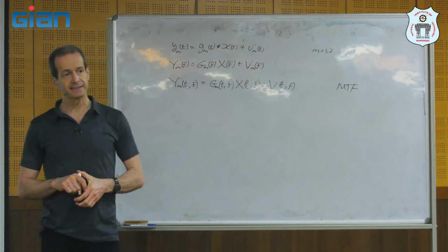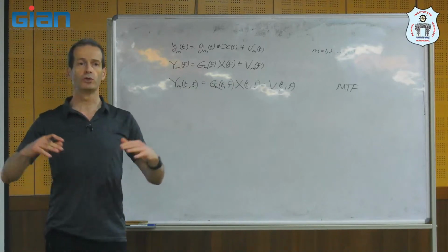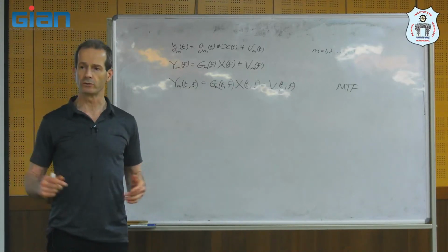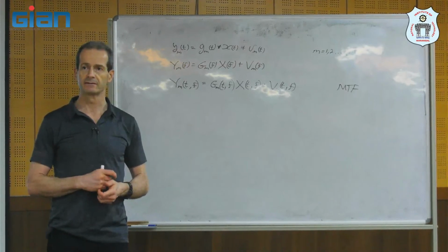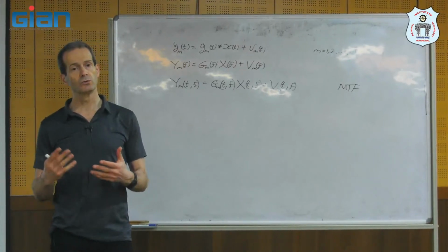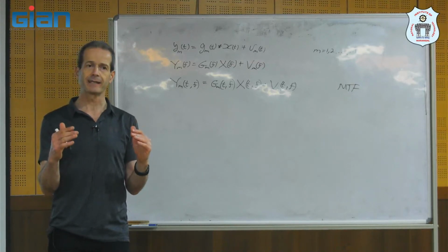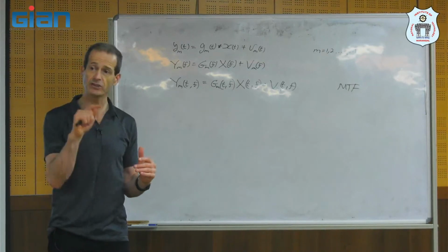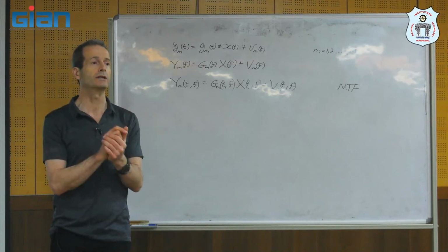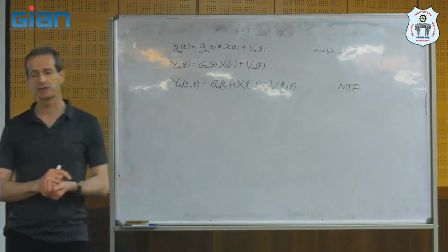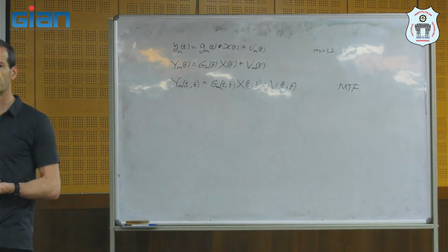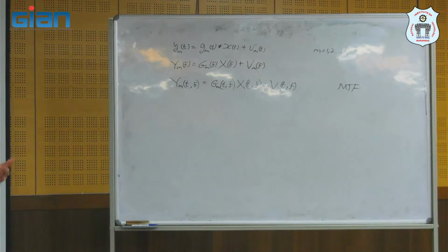So what we said, that sometimes you don't want to work with a long window in the STFT, because you want to work with a window such that the signals can be approximated as stationary during that window. For example, for speech signals, we work roughly with 20, 30, 40, 50, even maybe sometimes 60 milliseconds.